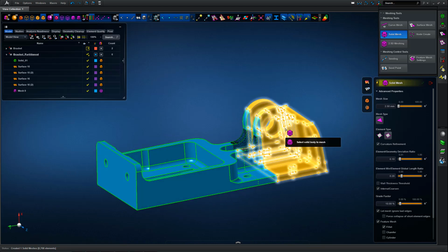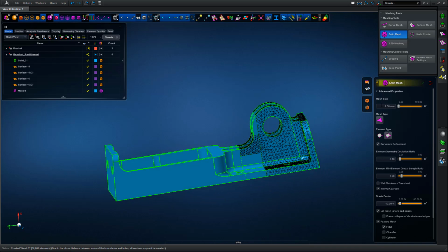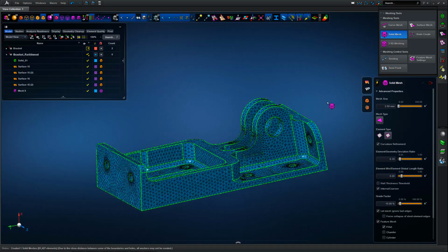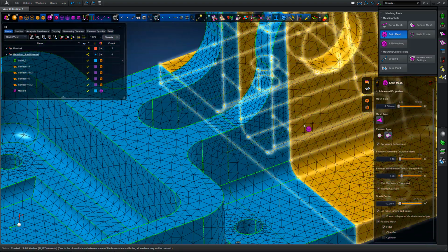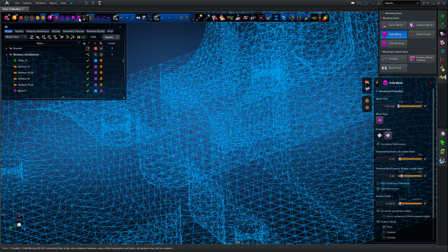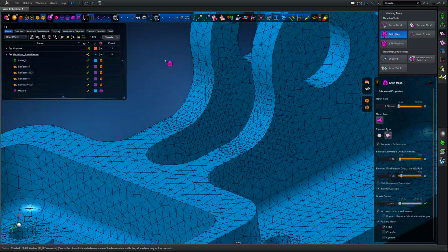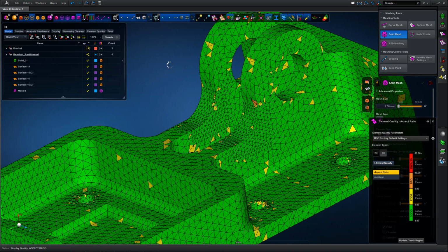Unlike the surface seeding approaches that we looked at previously, partitioning actually controls the element size going into the solid geometry that's being meshed. So ultimately we end up with better control on the surface and also through the thickness of the solid. We can see here the partitions now, all the partitions for a given mesh are fully defined, and we can see the transition from 1.5 mil to 2.5 mil across this fillet interface.